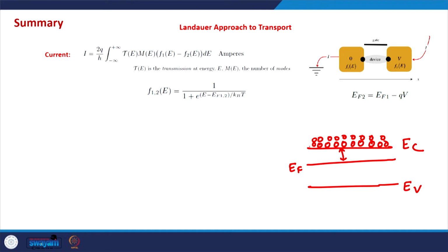And the energy of electrons, which is just above the bottom of the conduction band, is larger than EF, and it is quite significantly larger than EF, or it is many kT times. What we can write is E is EF plus kT times C, where C is a good number. C is maybe 9, 10 or maybe more than that.